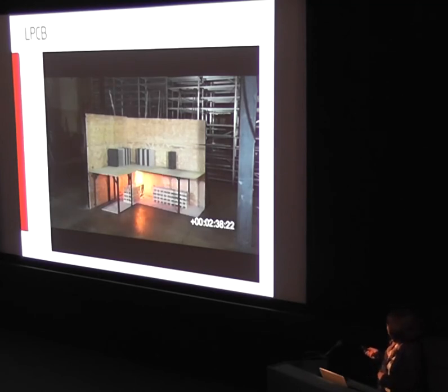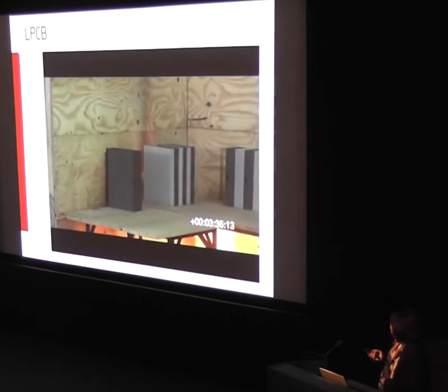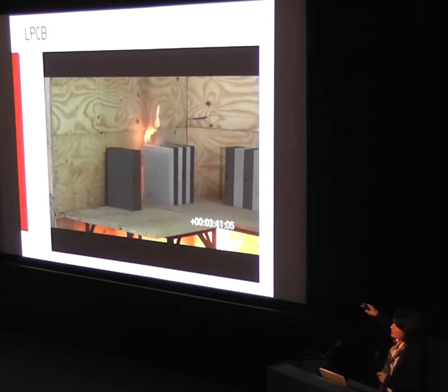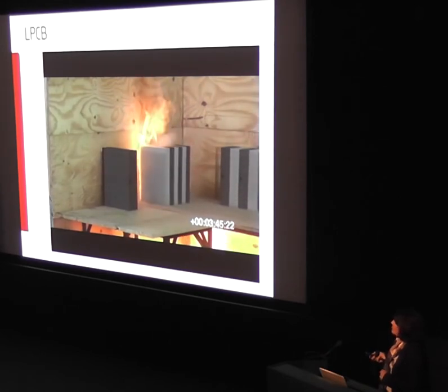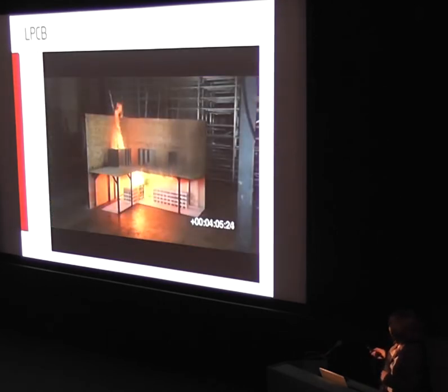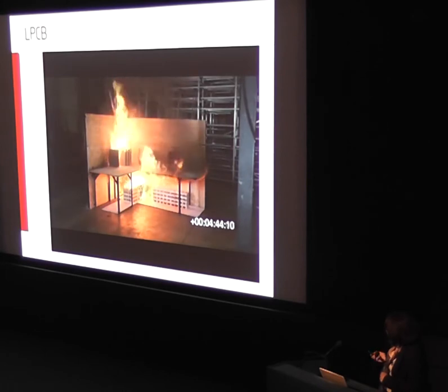I think we put it on YouTube so you can watch it at a slower rate at a later stage. In this test we had the ceiling at 5 metres above the crib. At the time of sprinkler operation, which is about 5 minutes, the fire has consumed half of this crib. It's burning up through the corner, and it's just about to spread to this crib here.